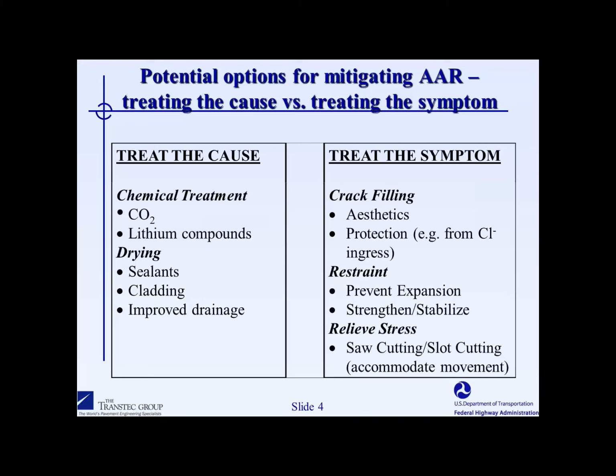So what we'll talk about now are kind of globally how we can deal with alkali silica reaction in field structures. And we can think of it simply as on the left side of the slide here, we can talk about treating the cause of ASR. And on the right side, we can talk about treating the actual symptoms of ASR. So when we're talking about treating the cause, I'll go through several of these in detail, but just in terms of this slide, there's a couple of chemical treatments that can be considered. One is that